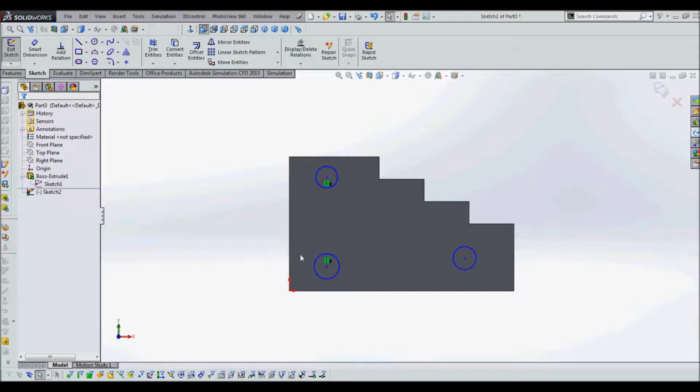You may note that if you're working on a very complicated sketch that some of these icons start to clutter up and get in the way of things. And if that becomes an issue that's problematic, you can use this command up here. So you see the small pair of eyeglasses up here. If you click on the down arrow here, there's a number of different icons. One of these icons is the View Sketch Relations icon, and if I were to click this, those will disappear. I recommend, especially when you're getting started and even later on, that you keep the sketch relations on so that you can see if something's breaking or if you're over or under constrained. Perhaps it's a relation that's getting in the way, or maybe you need to add more relations. So I like to keep them here for the purposes of clarity.